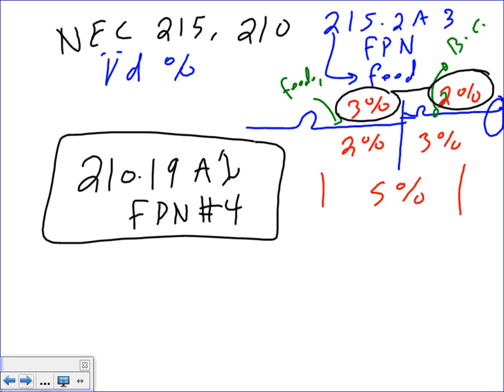This will tell you the same information for branch circuits. If you read it, almost the same information for branch circuits. Anybody has an issue with that? We're cool? So we established, we know where in the NEC code talks about voltage drop. We know it's unenforceable, but we enforce it just because we're engineers. And we're going to go 3-2 because most engineers go 3-2. Makes sense. Feeders are further.